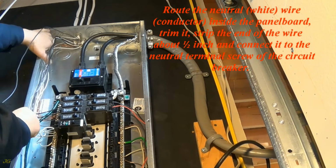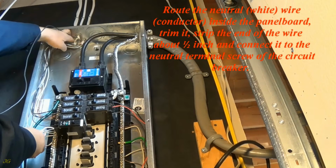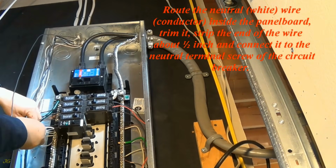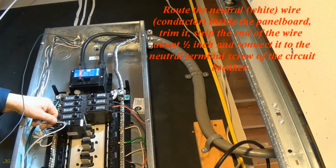Route the neutral, white, wire, conductor, inside the panel board, trim it, strip the end of the wire about 1/2 inch and connect it to the neutral terminal screw of the circuit breaker.